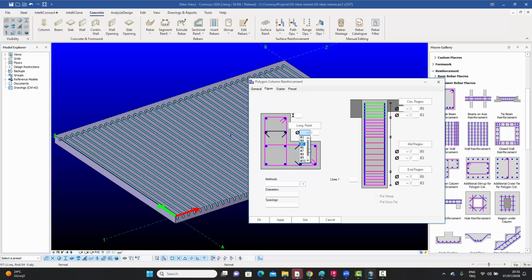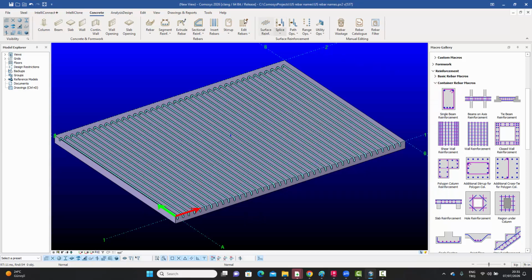So we've added the option of defining your bar names in the available steel diameters file, which is under the preferences menu. And there you can have a column with the bar diameters, and then another column for the bar names, and whatever bar names you put in there will turn up in all the container macros, the surface macro, even your parametric macros.